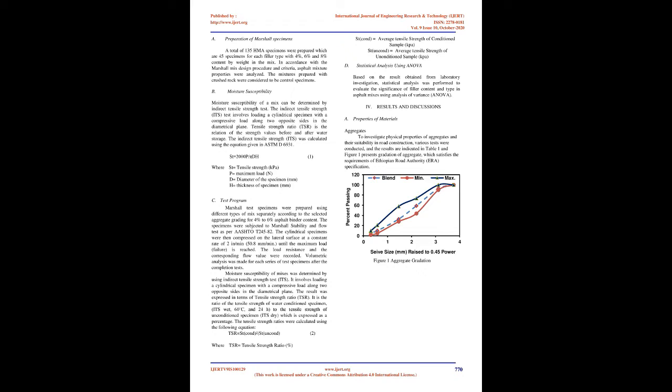Studied the influence of fillers on paving grade asphalt binder using three types of filler, namely cement, fly ash and stone dust. It was observed that unit weight and stability values increase from 4.5% to 5% asphalt binder content used and decrease for higher asphalt binder content. An increase in binder content yields decreased air void and increased flow value. Asphalt mixes prepared with fly ash show minimum air void and maximum flow relative to mixes prepared with cement and stone dust, and cement had maximum stability.